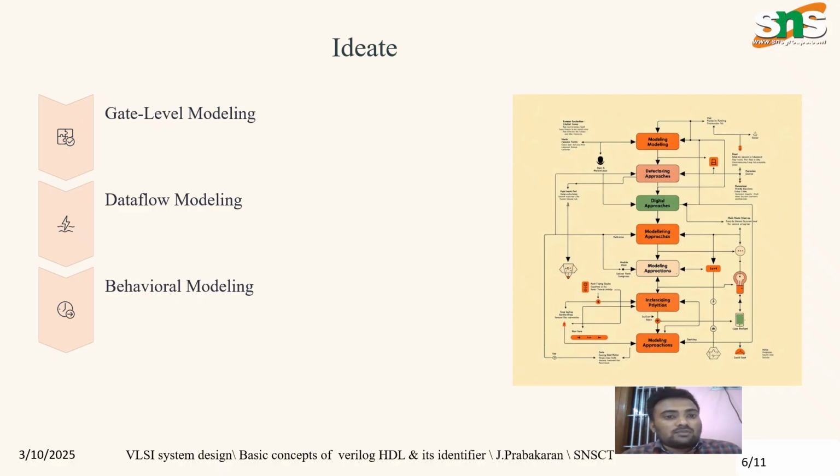Next is behavioral modeling, which uses procedural blocks, that means always block or initial block, to define high level behavior, either combinational or sequential logic circuits, describing complex sequential and combinational behavior at a high abstraction level. Designers strategically combine these modeling styles to achieve an optimal balance between code clarity and synthesis efficiency.